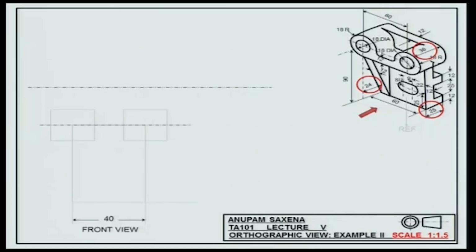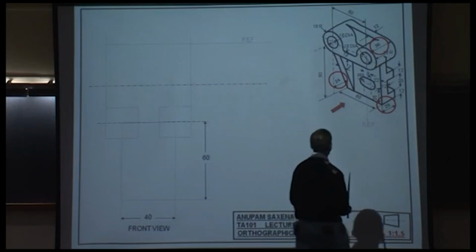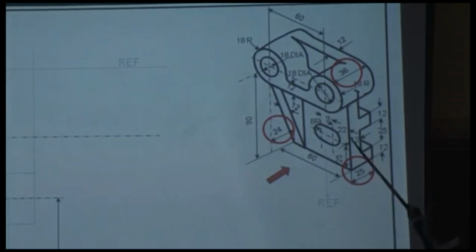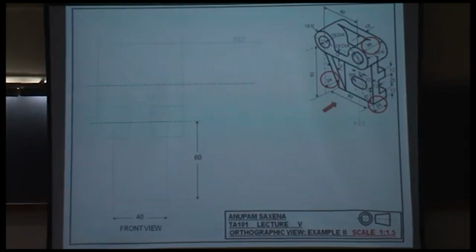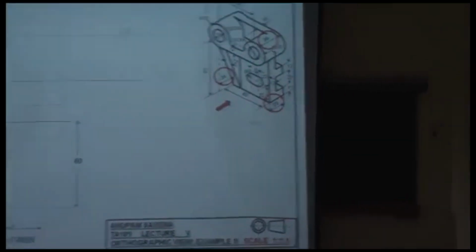What is this height? 90 times 2/3. Take the projections up. The first thing that you would want to draw in the top view is the reference plane. This plane. You would see that this plane is represented by a line in the top view.